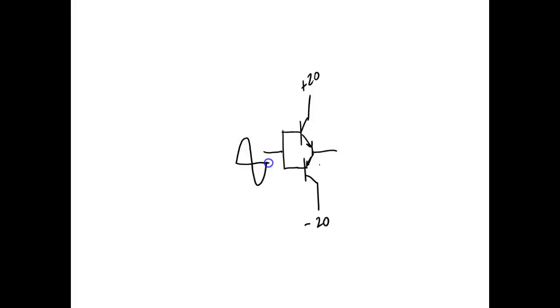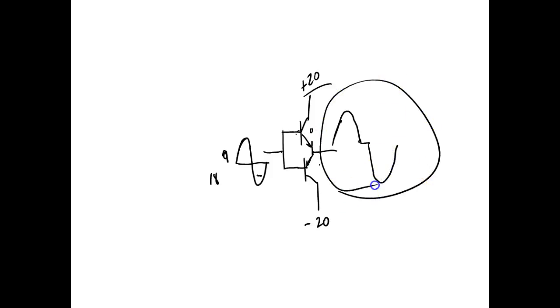So it means if I put 20 volts peak, I'm not going to put 20 volts. Can't get 20 volts. Let's say I put 9 volts or 18 volts peak to peak. Well, when this thing goes positive 9, it's going to cut this guy on and let this guy go through, right? And then when I turn this one, this guy is going to turn off and this guy is going to turn on. What is that right there? Is that DC or AC? That's AC. So using these guys, I can output AC, and then I can hook this up to an 8-ohm speaker.